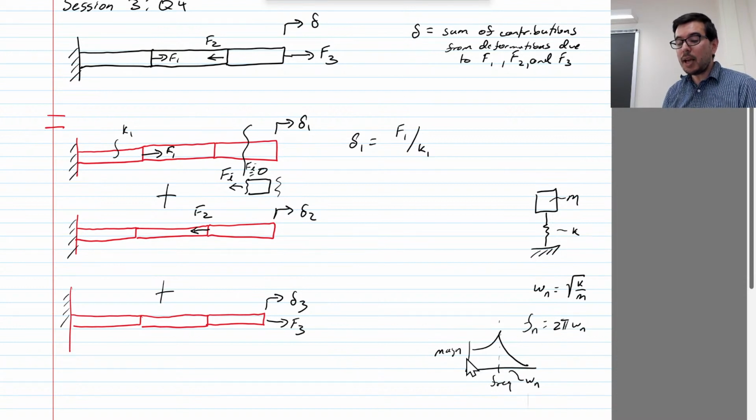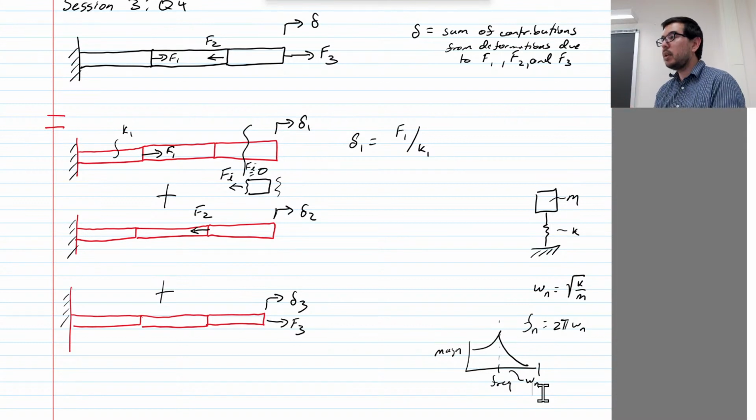Then they go through that resonance as it's starting up, and they operate out here. You see that? Because this is a second order system, it decays tremendously. The amount of vibration goes down quite a bit as you increase the frequency. For every factor of 10, you get a factor of 100 decrease. It's pretty cool.